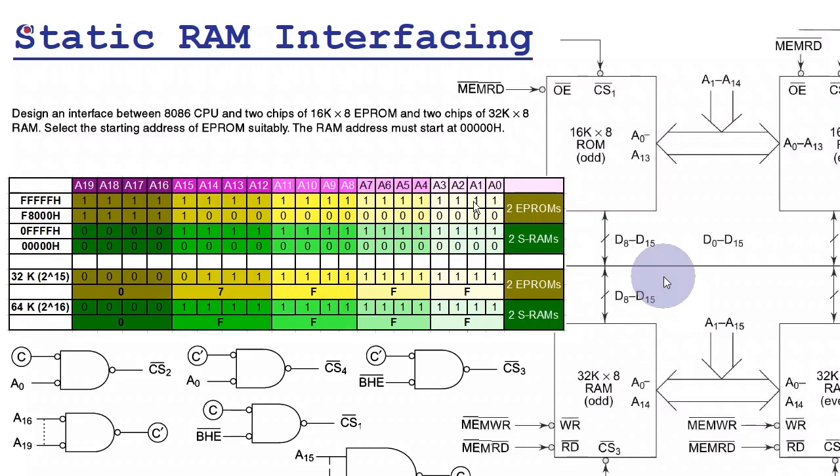For example, you might have seen in mobile phones that for a particular phone model you have a 16 GB or 32 GB variant, and the memory is expandable up to 128 gigabytes, right? The same happens with this microprocessor also. You do not interface the full 1 megabyte of memory. You interface only the part of the memory which is useful to you, and the remaining portions are either attached to some input-output devices or just left as they are. Why? Because memory is a costly thing, and if you try to use the full memory, it is of no use.